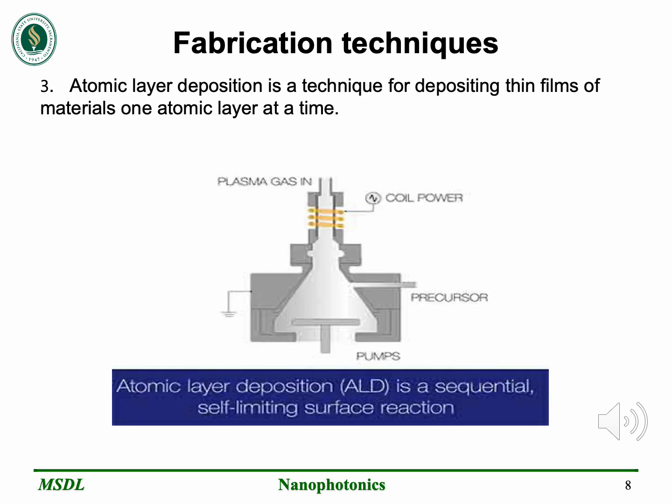Atomic layer deposition is a technique that allows the deposition of a material one atomic layer at a time. In this technique, the substrate is exposed to a precursor gas that reacts with the surface to form a single layer of material. The process is repeated for each layer, leading to the growth of a thin film with precise control over its thickness.